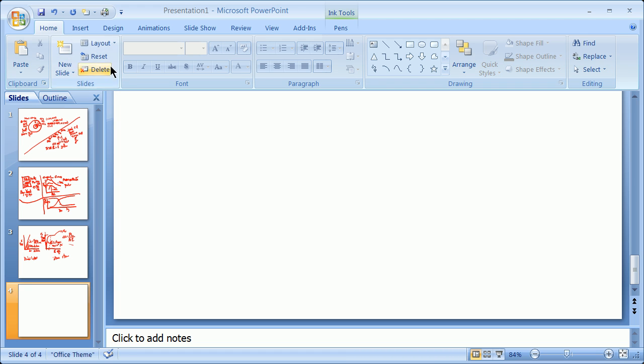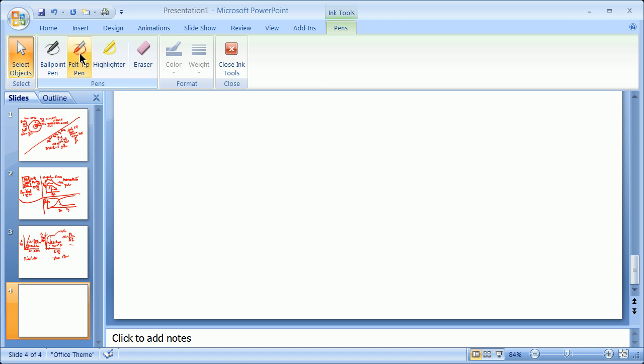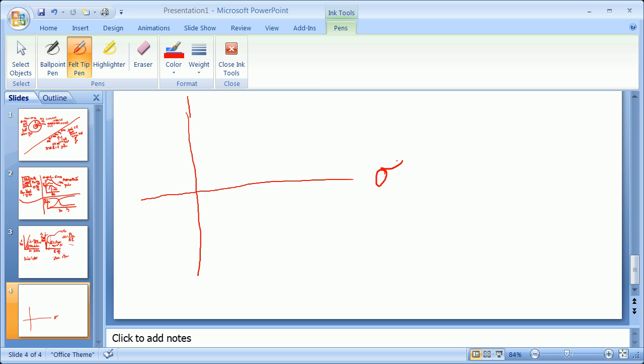And so the concept, as we go now once again to pens, that if we're going to do a Mohr's circle or a discussion of combined stresses, on one axis of our graph we put the axial stress or the normal stress, and on the other one we put the shear, so axial or normal, and on this one we put shear stress. Remembering that we make this assumption that in fact tension is positive and a counterclockwise spin is positive. So tension is positive in both cases, along the axial stress, and counterclockwise is positive.